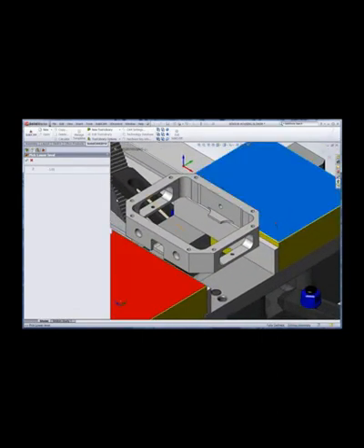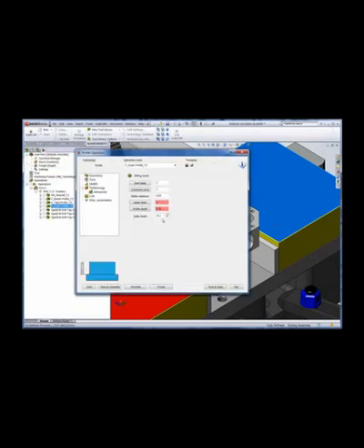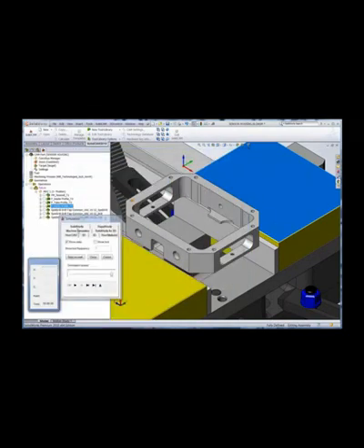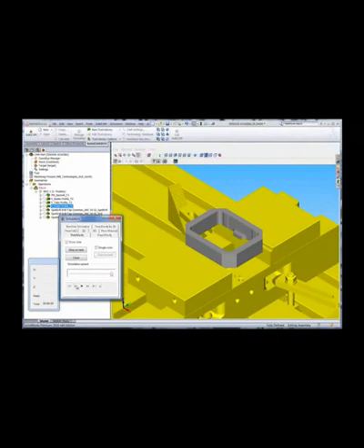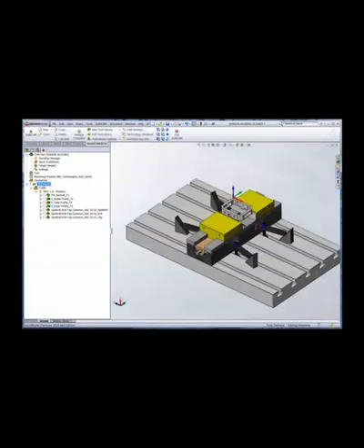And in this case, we notice that the outer profile has inadvertently crashed into the fixture. Notice it shows us what operation this occurs in, and we can choose whether or not to continue monitoring. I'm going to say don't monitor it anymore, but also notice that the system now shows us the red indicating that this has gouged our vise.